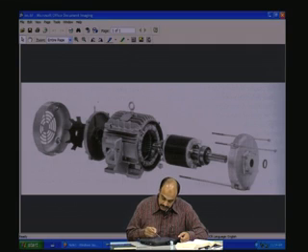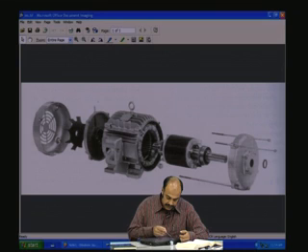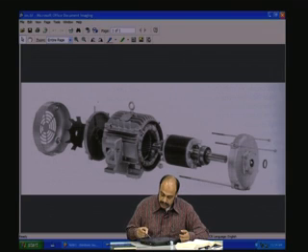And this rotor is inserted into it, and then you have the end facing plates. These are the end plates here. This is one end plate and this is the other end plate, fitted in through these bolts, and then there is the bearing, which you see here, which fits into this and will cause a smooth rotation of the shaft.